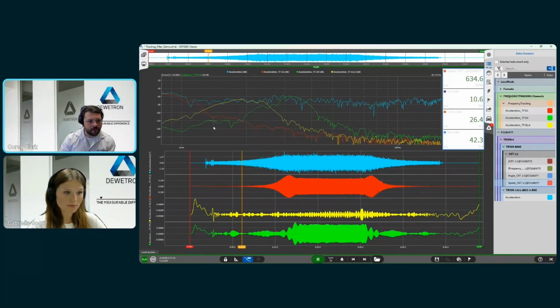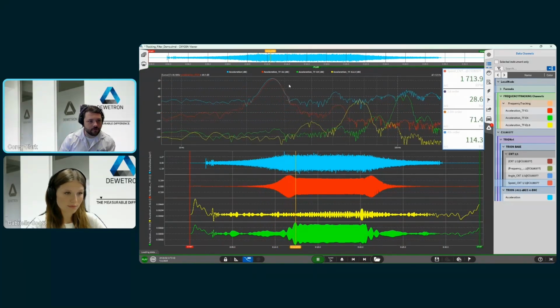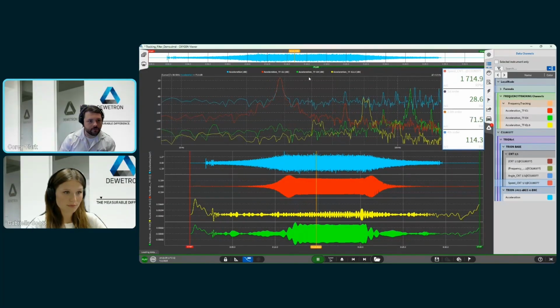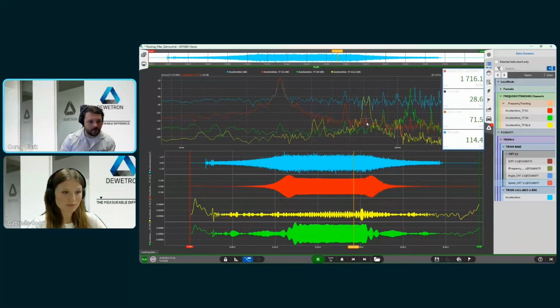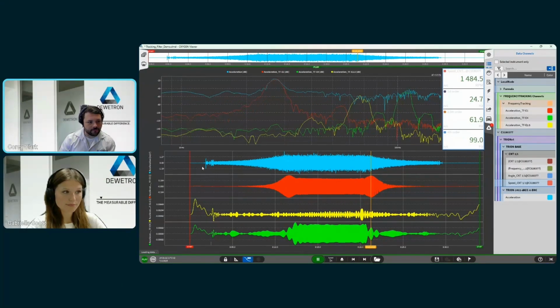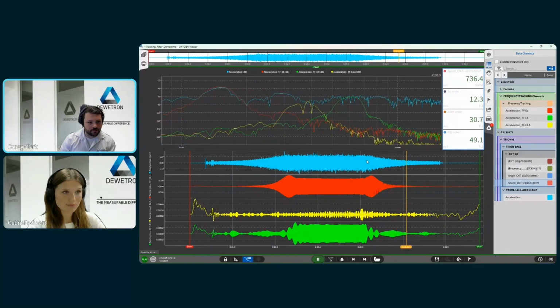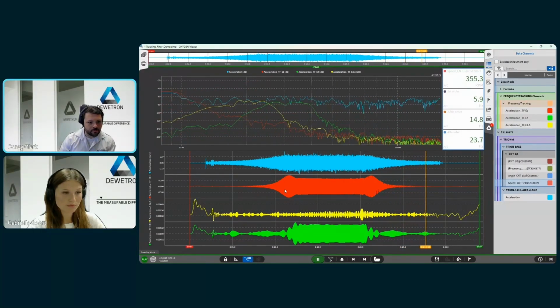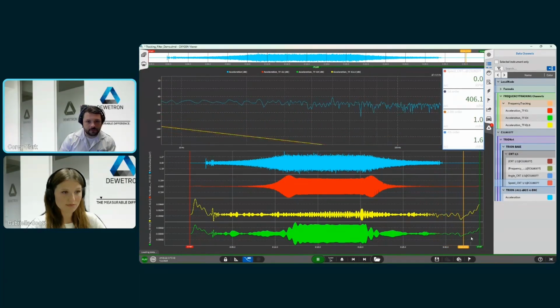Inside the spectrum analyzer at the top, we have our acceleration signal in blue, the raw one, and then we have the first order, the fourth order, and the 2.5 displayed alongside of it. You can see this information down below as well in the time domain. So you can see the raw acceleration signal and then the extracted order information for that same accelerometer signal. And this is all based upon the running speed of the device under test.